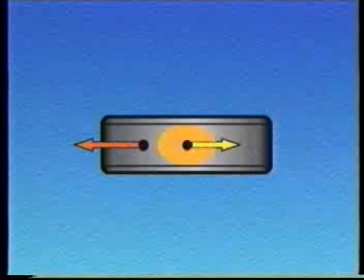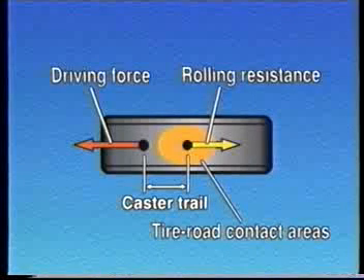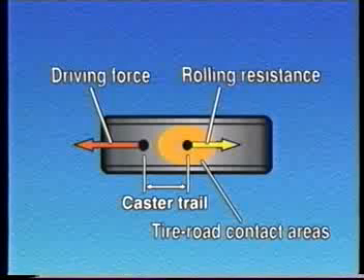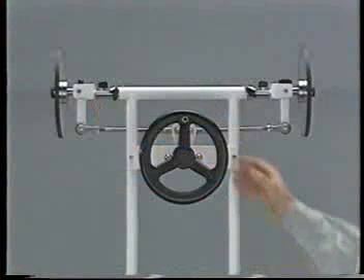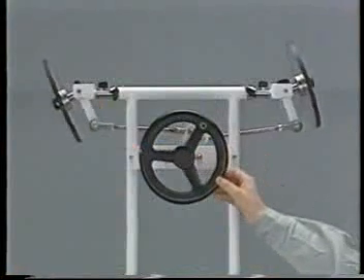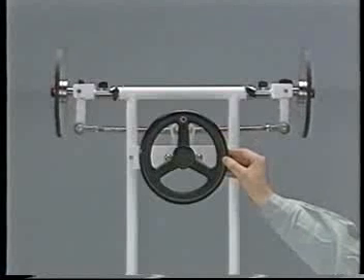This figure shows the composite force acting at the wheel-to-road contact area, represented by the circle. The tire friction at the center of the wheel-to-road contact area opposes the forward-acting force by the trail amount. This provides stability while driving straight. When this principle is applied to an automobile, two wheels should be considered at the same time because the left and right front wheels are connected.